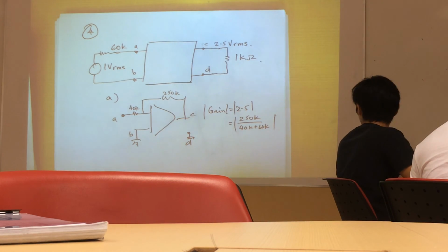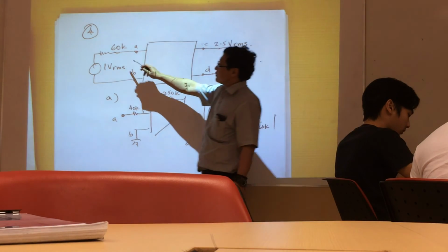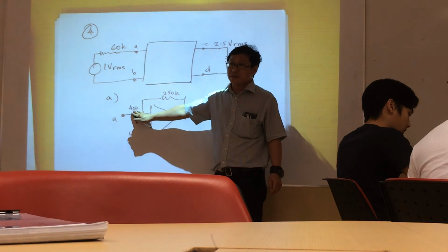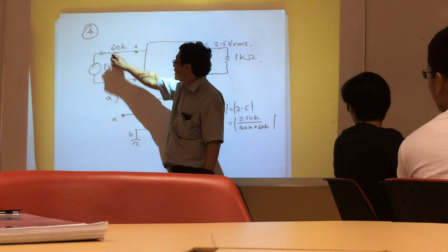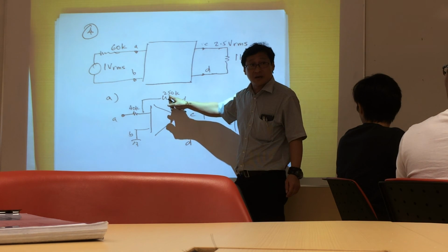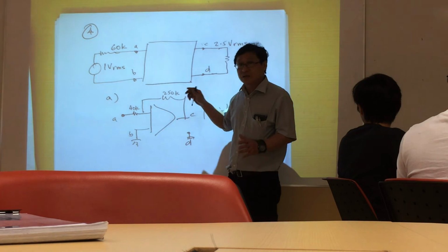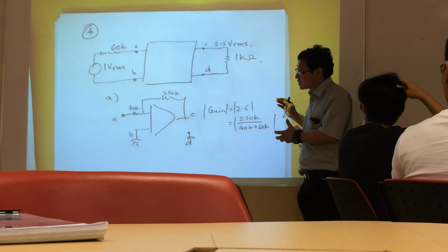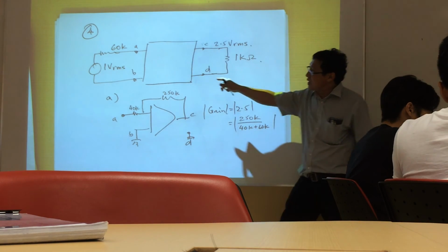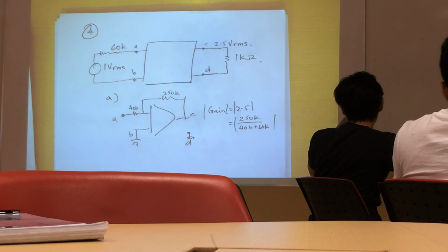Of course, the selection of the resistor is very limited because of the fact that you have this 60K here. Right? Because of this 60K, we have a limited choice of resistor. We could remove the 40K. If we remove the 40K, then the 60K becomes the resistor that is connected to the inverting input. And therefore this resistor becomes 150K because 2.5 times 60. Right? So again, if you look at it, the selection of the resistor is very limited. By the way, this is a minus here. Alright, it's very limited because we have a source resistor connected to it already. Therefore, the limitation is fixed by that. Alright, so limited choice.